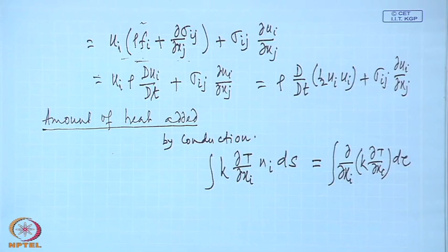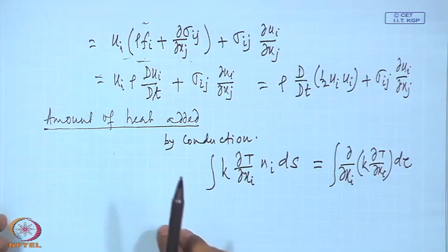We are considering towards the system, because you are adding heat to the system, that we have taken as positive. If you look at that first equation we wrote for the first law of thermodynamics, dE equal to dq plus dw, both we have taken what is added to the system as positive. Okay, what you are saying is correct.